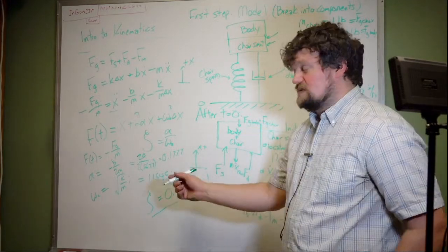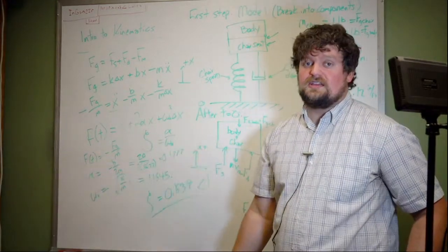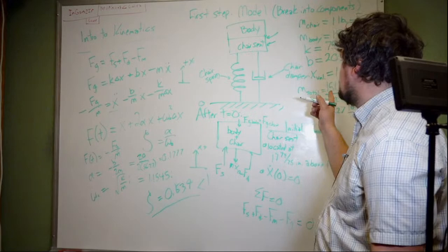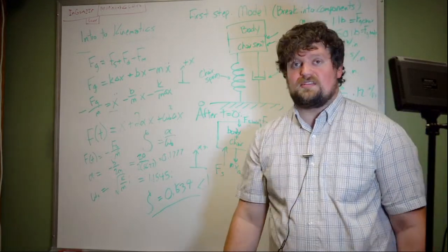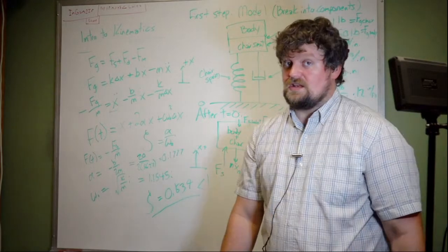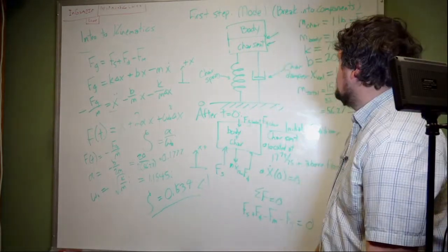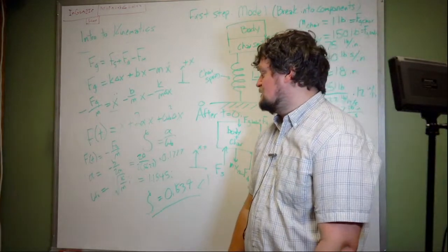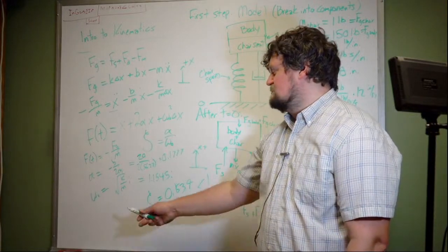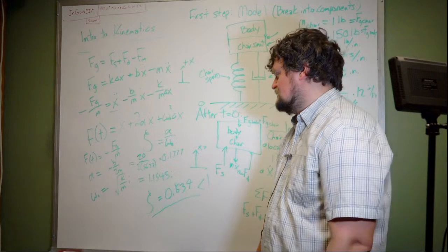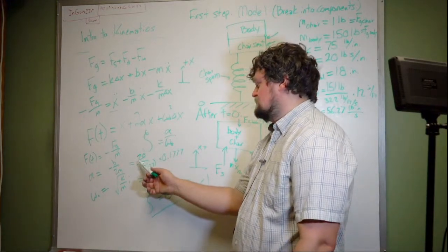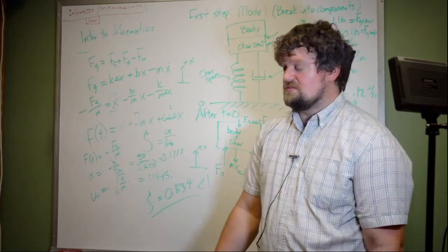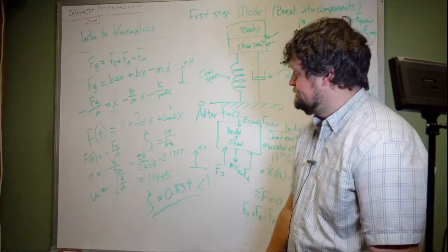What you're going to have happen when you sit in your chair is you're going to oscillate. Okay, and that's actually what kind of happens. You bounce in it. A good chair will have a strong enough damper that it won't do that, but apparently this is not a good enough chair with the values that I picked. This probably should be closer to 2,000 pounds, but yeah, we're good. If you just increased the b value, that would change your zeta significantly. It just needs to go from 20 to 200, and then it's more critically damped. Should be nicer, but you know, whatever.